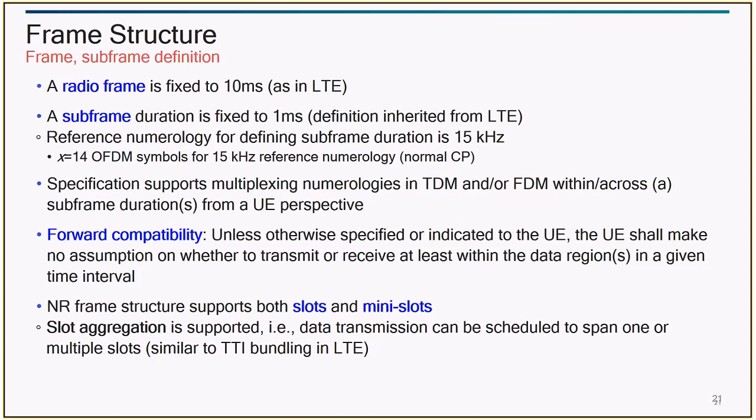Then you should also change your subcarrier spacing. The subcarrier spacing, I have assumed it to be 15 kilohertz. Now when I increase my subcarrier spacing from 15 kilohertz to 30 kilohertz, the number of slots available doubles. So instead of 7 slots at 15 kilohertz, I would get 14 slots. Slots are variable. So in 30 kilohertz I can have more data coming in, more symbols can come in, so my number of slots increases.